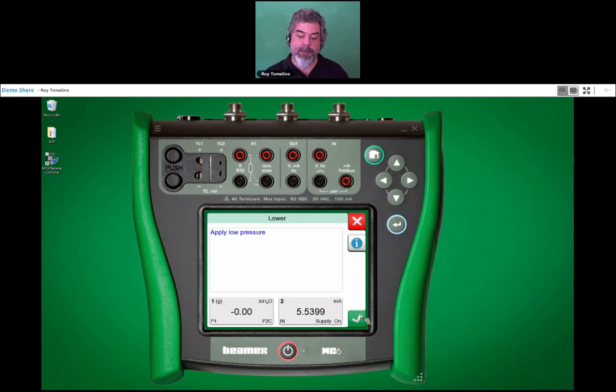Now, everyone, watch the 5.5. I'm going to hit the check mark and... all right, so keep watching. It's stable now. So I'm telling it that I'm at zero. Actually, this is where I tell it. I got a little ahead of myself. So I need to tell it I'm feeding you zero, so you should change this to 4 milliamps. So I'm going to hit the check mark, and it's self-correcting. I've told it I'm feeding you zero, and it's really zero, and it made 4 milliamps the answer. So let me hit the check mark.